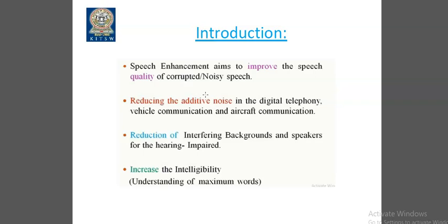Reducing the additive noise in digital telephony, vehicle communication and aircraft communication. Reduction of interfering backgrounds and speakers for the hearing impaired, and increasing the intelligibility. Intelligibility is nothing but, whatever sentence is spoken by the speaker, we must understand each and every word of the sentence. So how many words we are able to understand comfortably, we calculate that as the intelligibility.